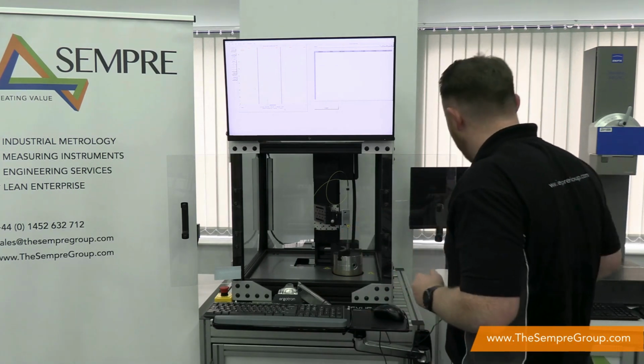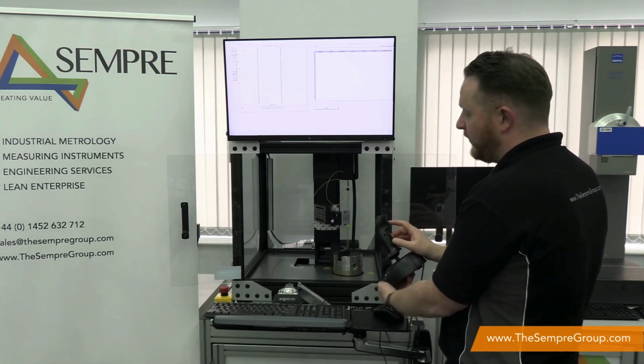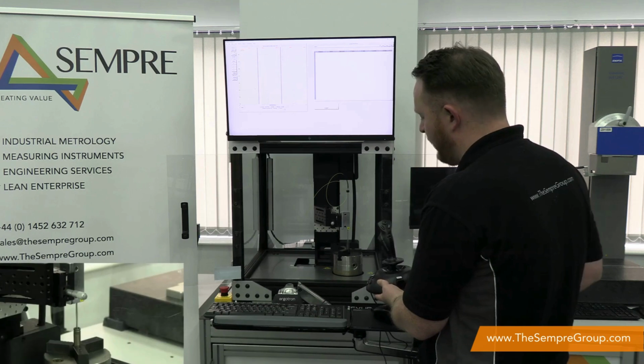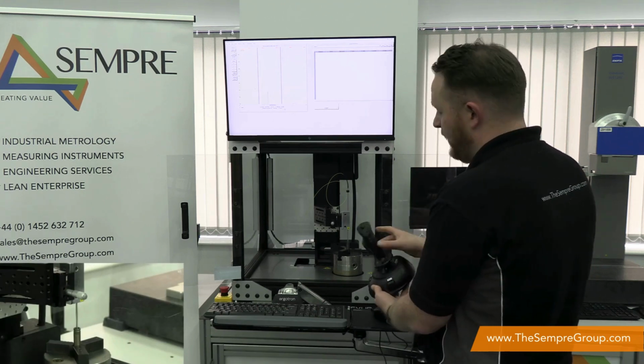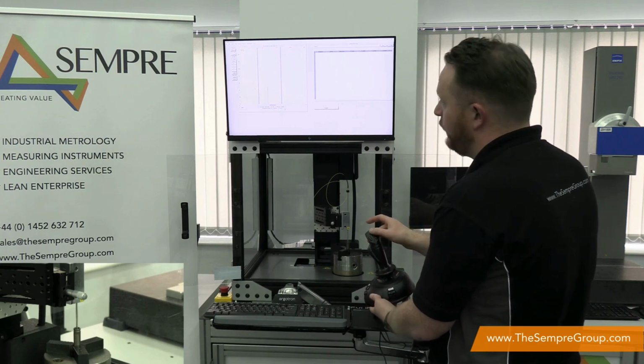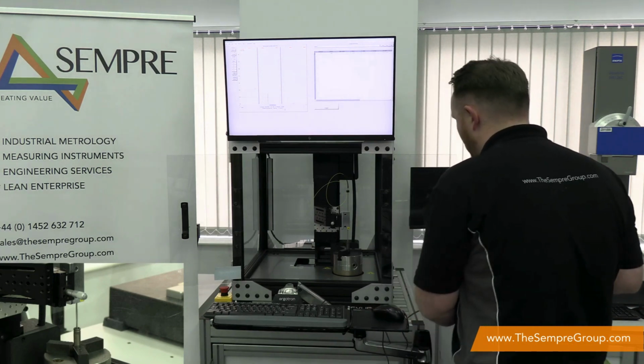Okay, so now I've got the sensor in the correct position. What I'm going to do is click the back button on our joystick here. I'm now going to drive internally in the component to my finished position, and I'm going to click this button again. And then on the top of the controller, there's a number 2 button, and what that does is it inputs a scan definition into our code.